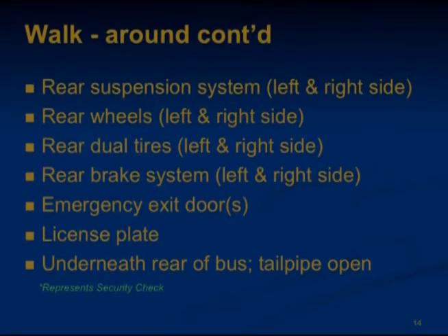Make sure that there's nothing between the tires or the spacers. On rear brakes, sight check the chambers for damage. Air hoses are secure on both ends, pliable and not leaking. Manual slack adjusters, brake rods should not move more than 1 inch when pulled by hand.